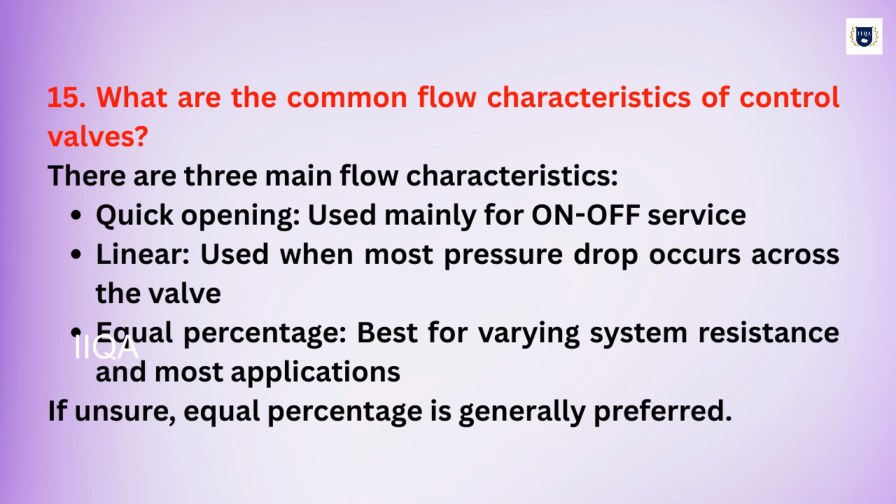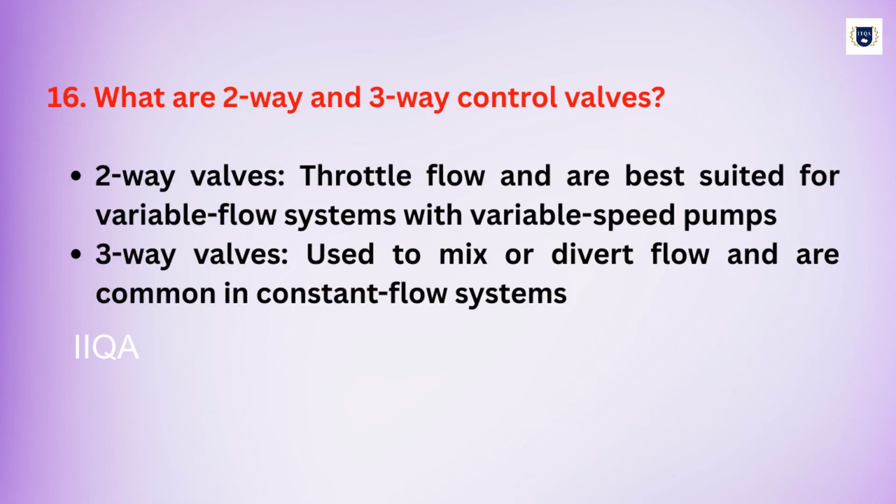What are the common flow characteristics of control valves? There are three main flow characteristics. Quick opening, used mainly for on-off service. Linear, used when most pressure drop occurs across the valve. Equal percentage, best for varying system resistance and most applications. If unsure, equal percentage is generally preferred.